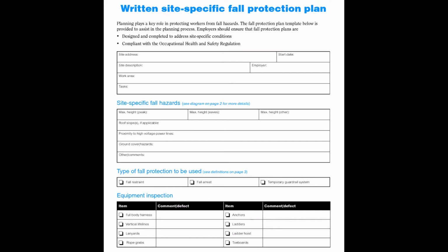A copy of the fall protection plan with all approved changes shall be maintained at the job site. The implementation of the fall protection plan shall be under the supervision of a competent person. The fall protection plan shall document the reasons why the use of conventional fall protection systems, guardrail systems, personal fall arrest systems, or safety net systems is infeasible, or why their use would create a greater hazard.